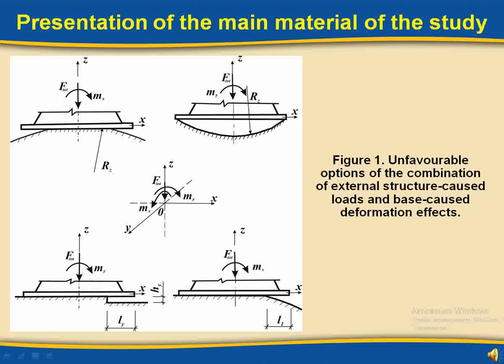Further deformation of the base changes the physical and mechanical characteristics of the soil; the bearing capacity and the stiffness of the base are reduced. At the same time, the soil deformation curve in the new state does not coincide with the first curve. Therefore, when solving the contact problem for these conditions, it is necessary to take into account the differences in the soil load curves for different points before and after the weakening of the base.